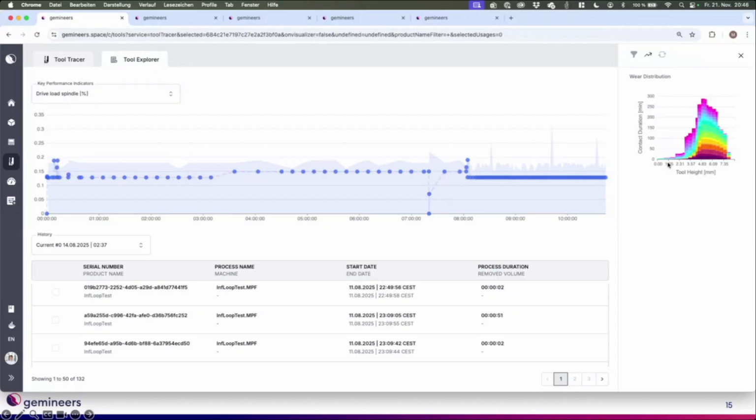And I think this would also be one of the next questions. Can we trigger a sister tool change just based on the tool data? Not yet. Also, one of the next steps is to say, okay, use this instead of your 200 minutes in material, because you know this is the safe number. Use it until a specific limit, and then change it, because sometimes your experience is not good because there was more material on your cast iron or something like this, and you hit a cutting edge badly. So yeah, still a lot of stuff to do.